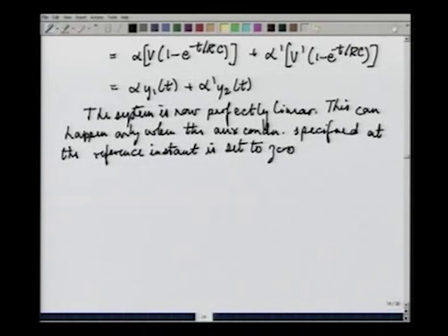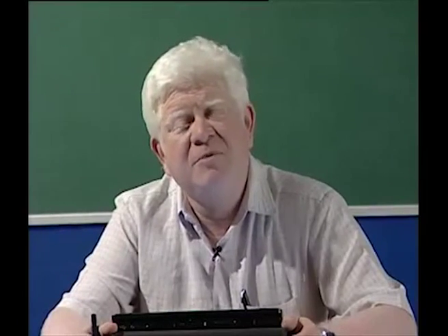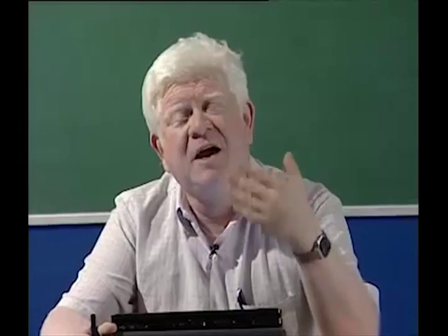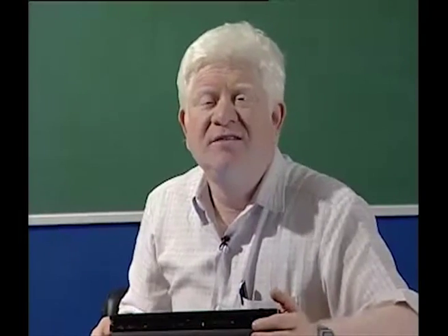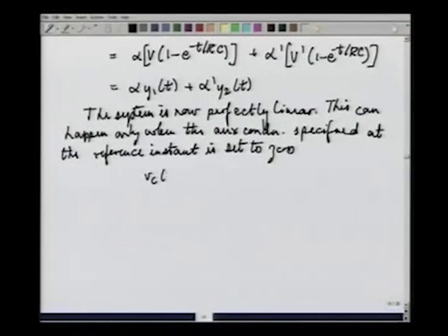All right. Now, let us just explore this from a different angle. Since the ultimate unique output y(t) is determined or affected both by the input signal V or x(t) as well as the auxiliary conditions, suppose we try to explore the relationship between possible changes we apply in the auxiliary condition and the corresponding outputs that result. Going back once again to this pet equation of ours, Vc(t) equals V0 minus V e to the minus t by RC plus V.